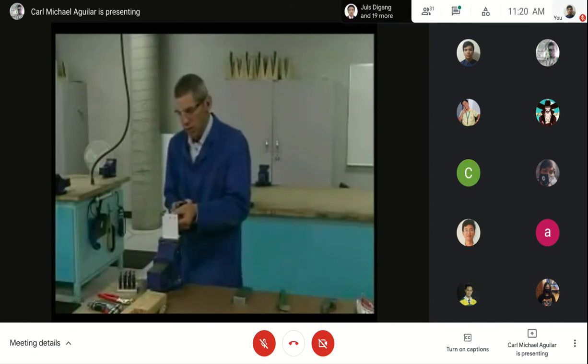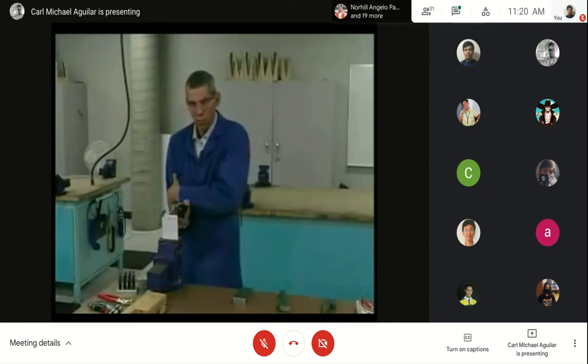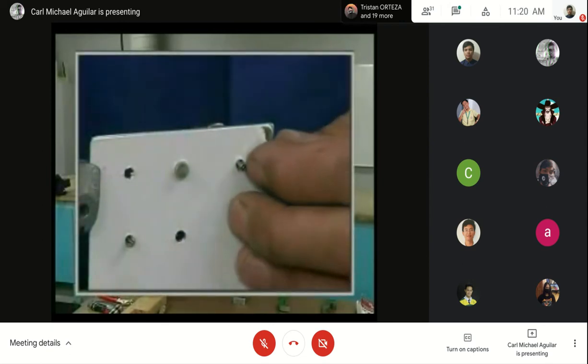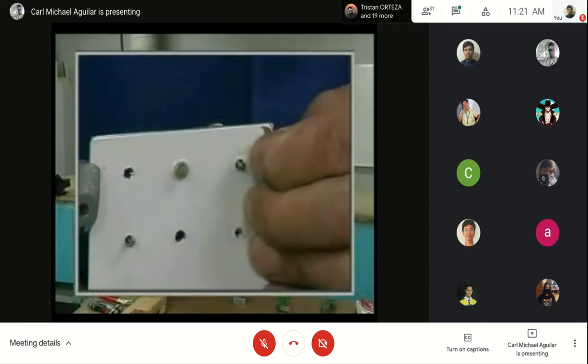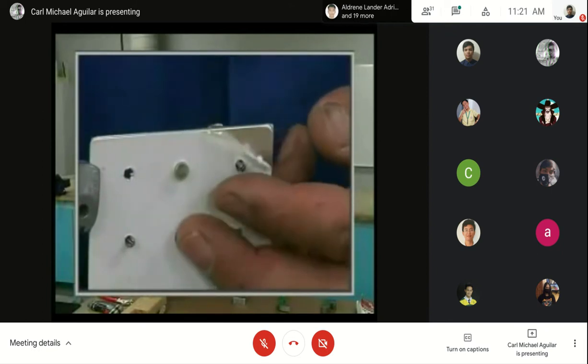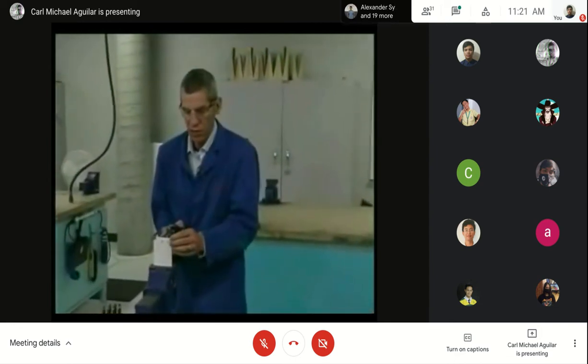Positioning my body, I like to have my knees slightly bent, my body nice and square to the work area where I'm working. I like to support, if I can, the rivet gun using my free hand onto the aircraft. I like to keep my wrist nice and straight, and my arm into my body for control. For demonstration purposes, I've left the protective plastic on the sheets so that you don't get glare on the video from the lights. But normally, the protective plastic would have to be removed from the sheets, obviously in between, as well as on both sides.